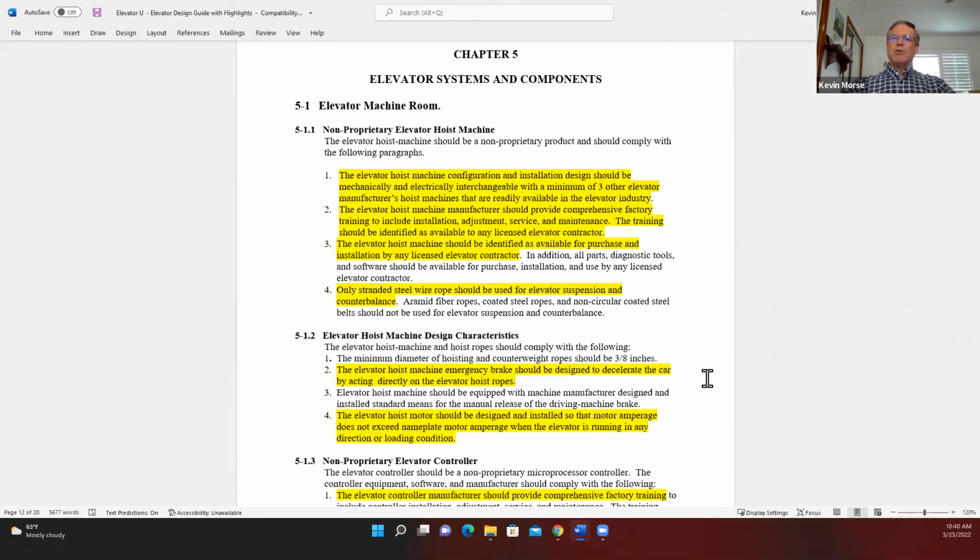I'd say all the elevator people that are listening in and participating in this webinar know that one of the ways that an elevator can be out of control and moving up or down the hoistway after the drive machine has stopped and the drive sheave has stopped is by the hoist rope slipping traction.